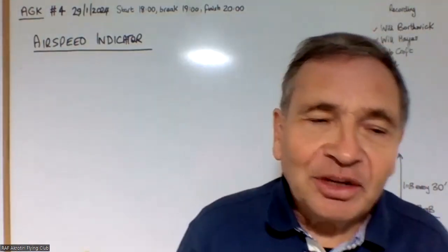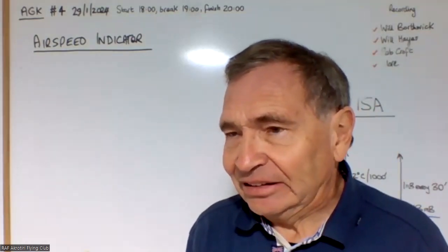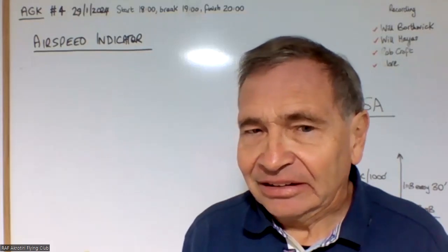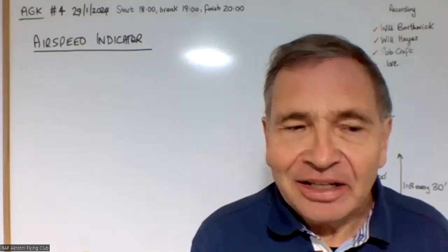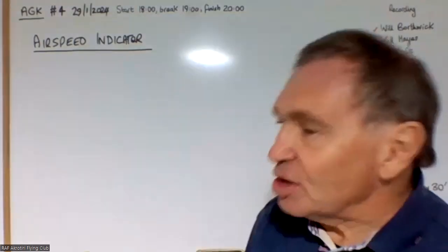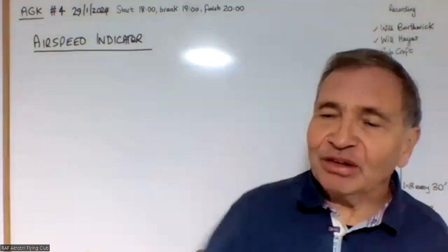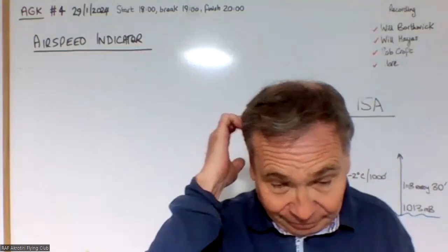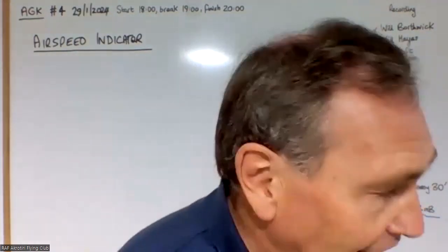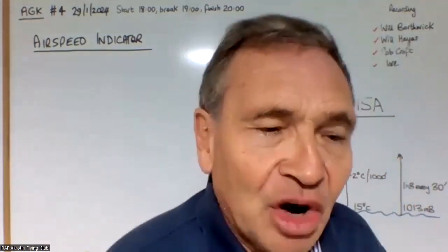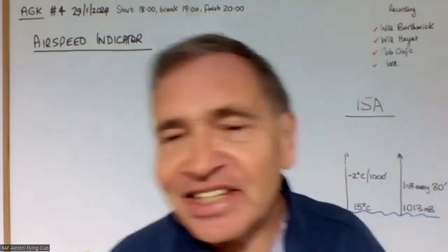Okay. Well, what are you going to do about it? Quick. Well, you can't take off. Emergency land. Well, you're already on the ground. You're running along. Vacate the runway then. Well, you just abort the takeoff, don't you? So, in other words, you just bring the throttle back, bring the plane to a nice halt on the runway. Tell air traffic control that you've aborted, and you're vacating by the next taxiway.